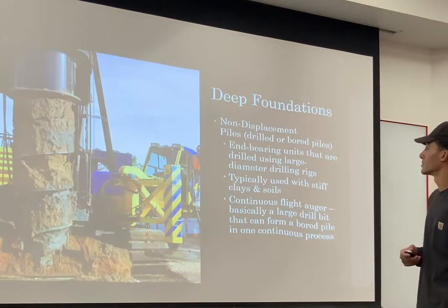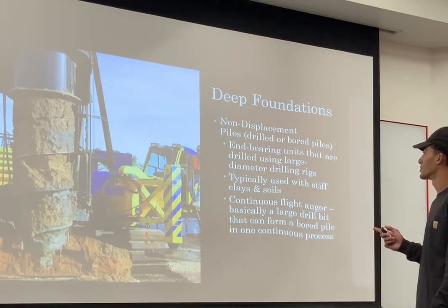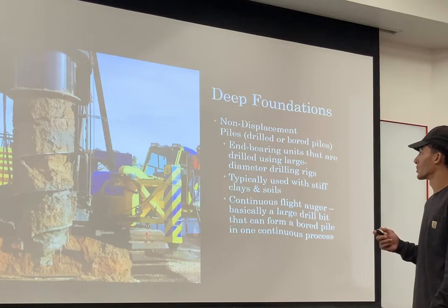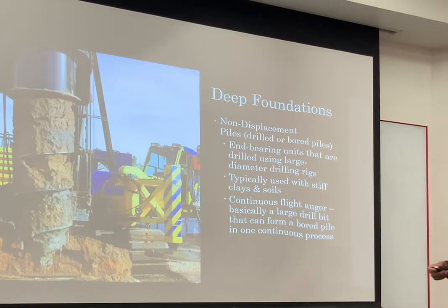Deep foundations: non-displacement piles, drilled or bored piles. These are used for load-bearing units that are drilled using large diameter drilling rigs, typically used with stiff clays and soils. They're also continuous flight auger, basically a large drill bit that can form a bored pile in one continuous process.